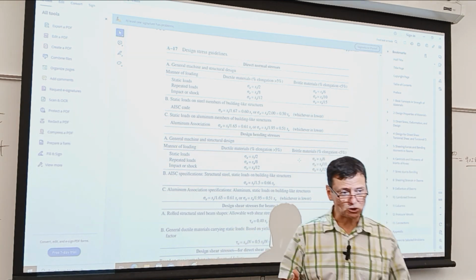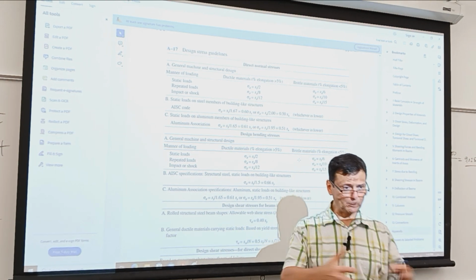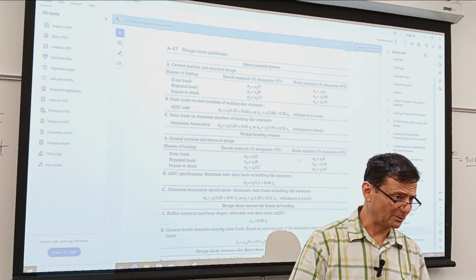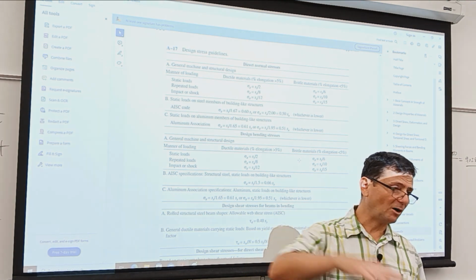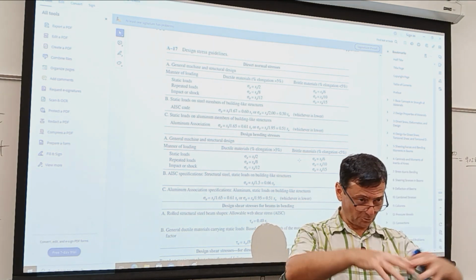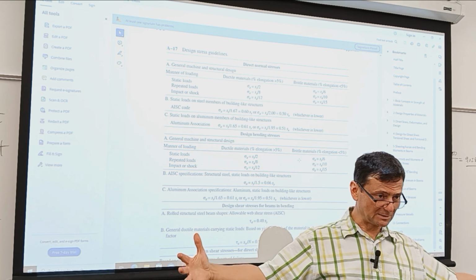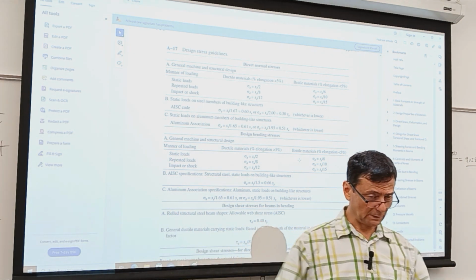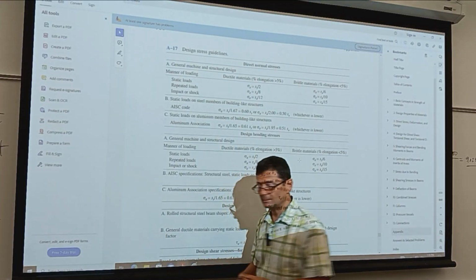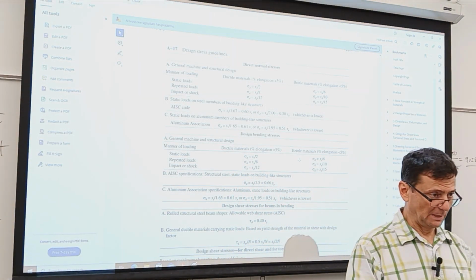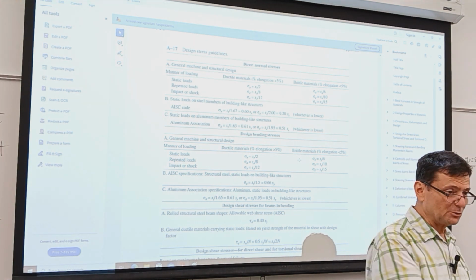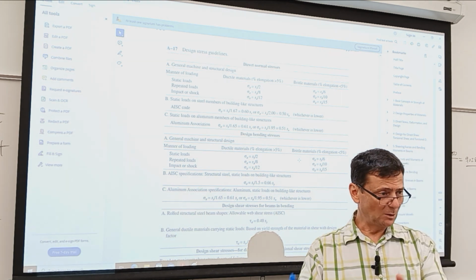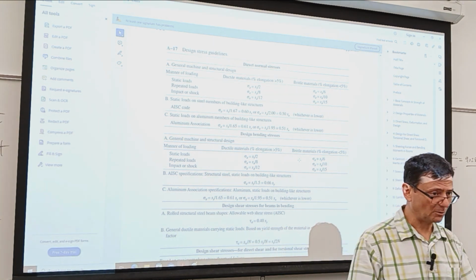Aluminum does not have what is called infinite fatigue life. So airplane frames, it might be more than that. I think they fly in the neighborhood of 30,000 hours. Usually it's the takeoff and landing cycle, and then for the body, because it's pressurized and outside is low pressure, and then coming back to equal loading. Anyway, for aluminum, because it has been used for quite some time in the aerospace industry, they know more, and they know, okay, this frame, you fly only 10,000 hours, and then you scrap.